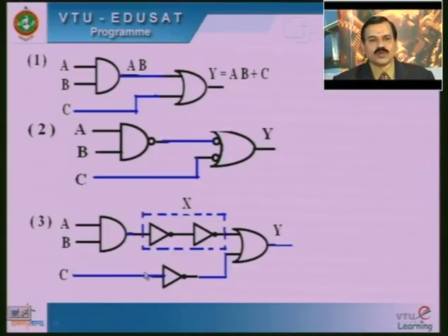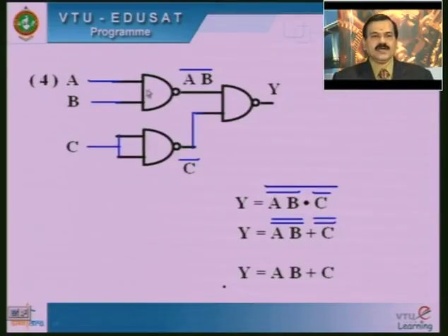The input is only one terminal, because if you are using a two-terminal input NAND gate, the two input terminals are shorted and connected to A, and only one single output is connected to this termination, that we are seeing in the next. So here all the three remaining gates, the NOT gate, the AND gate and the final OR gate, whatever circuit remains after cancellation of the inverter gates, all components of the circuit must be replaced by NAND gates.